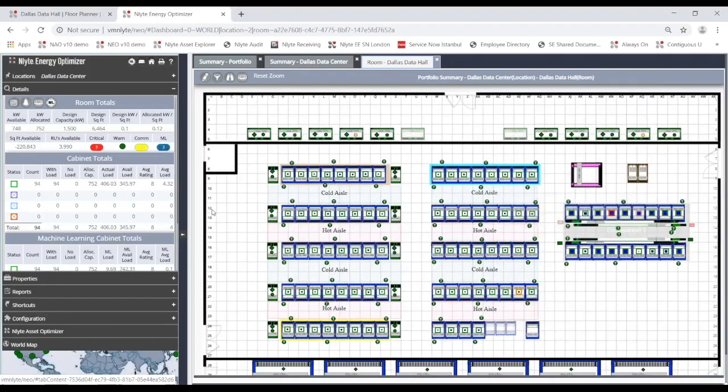But here, we are able now to monitor PDUs. As you can see here in the corridor outside of the main data center hall, we have the A side PDUs, the B side PDUs, and then we also have RPPs that are supporting the circuits that are going to, in this case, in this area, cabinets that are supported by in-rack power strips. In this area, we're showing cabinets that are supported by branch circuit monitoring, and this is busway. So those are the 3 main ways that we're able to get down to actual circuit power distribution into the data center.